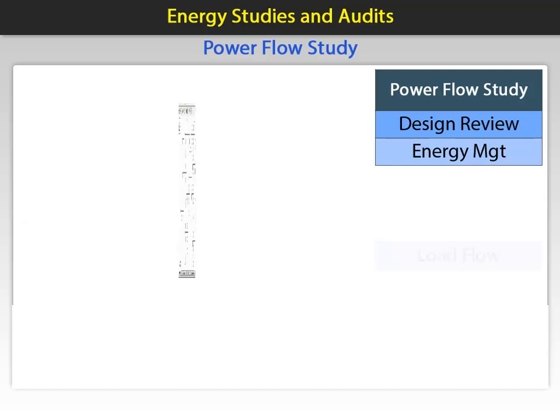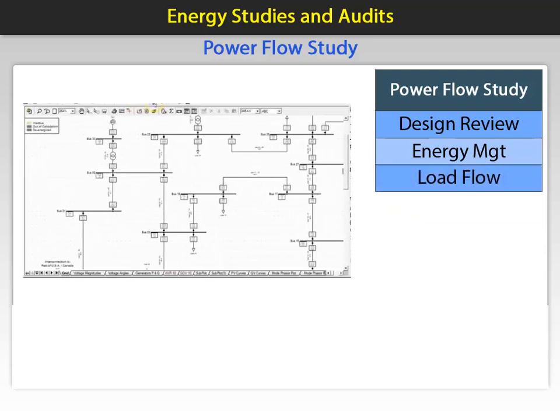Load flow analysis determines how power is distributed across an electrical network. It helps in optimizing voltage profiles, reducing losses, and preventing overloads. There are a few methods for studying. One is to use power flow simulation software like PowerWorld and DIgSILENT to calculate bus voltages, line losses, and power distribution. Perform N-1 contingency analysis to assess the system's ability to withstand a loss and what backup is available. Evaluate voltage stability margins to prevent system collapse.